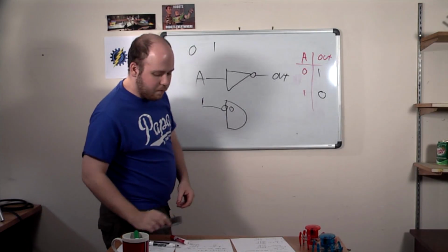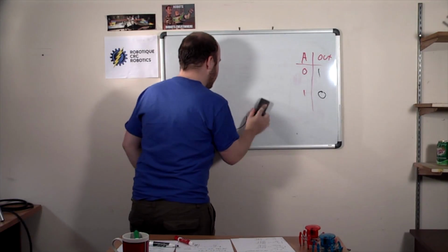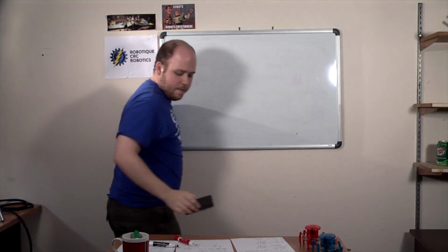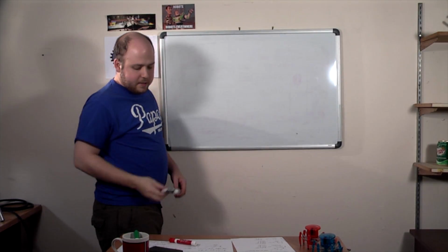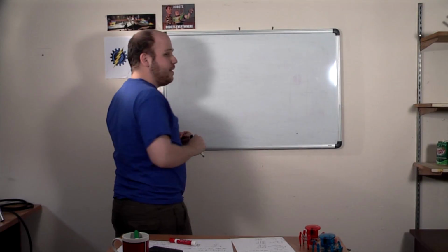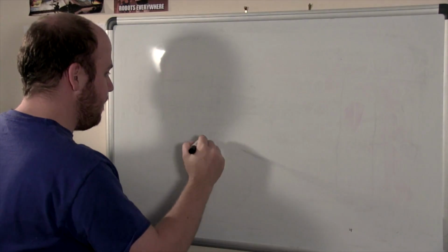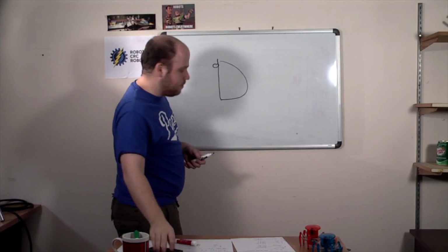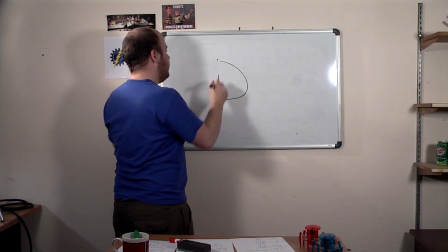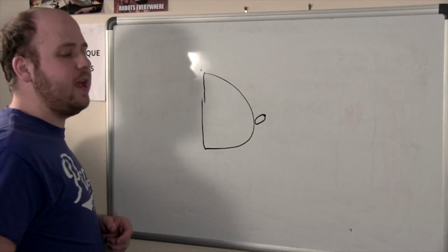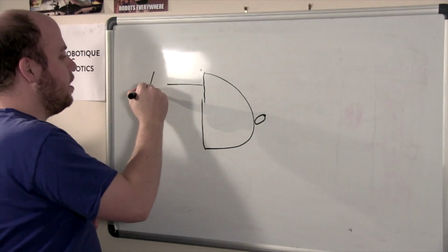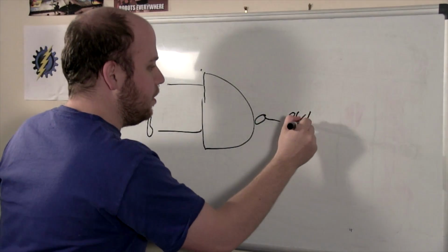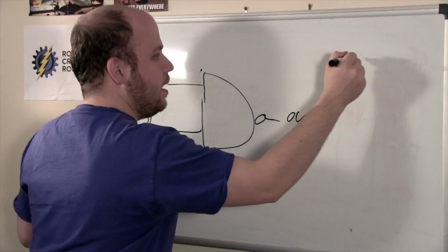Let's take a look at one example of an inverted gate. It's called, and we'll draw it. So, okay. It's called the NAND gate, NOT AND. So we'll start with the classic AND gate, but we'll reverse the output and see what is going on. So we have A over there, once again B, and your classic output over there.